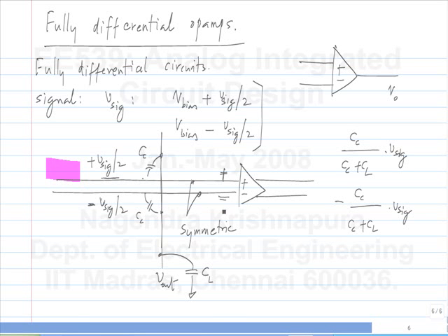Okay? Now that is an important thing that is left to the amplifier. The amplifier should be sensitive only to the difference. It should not be sensitive to the sum of the two signals. Okay? And as I mentioned earlier, that concept is the common mode rejection. So because of this, every signal is routed as fully differential signal. Okay? So that basically means that you will have less interference going around. So that is one type of thing. When you have interconnects, there will be less interference injected and also there will be more immunity to interference.